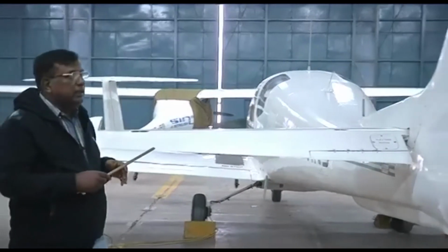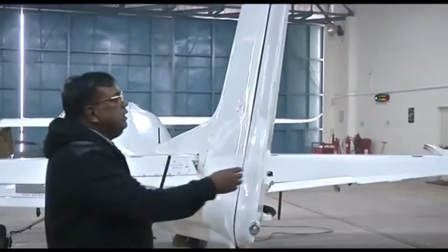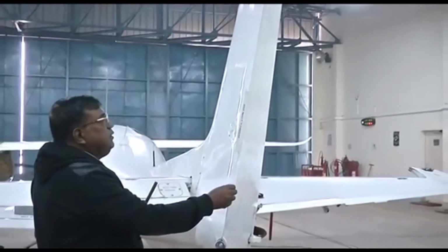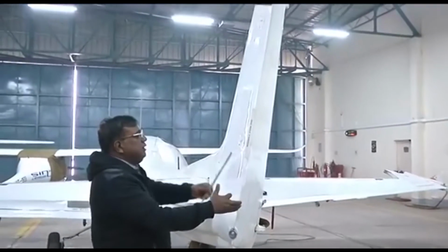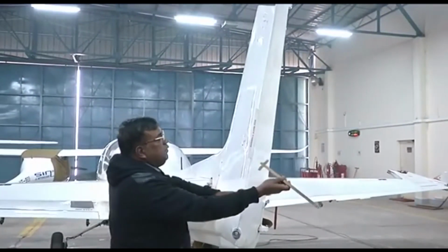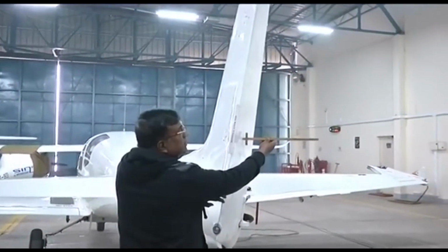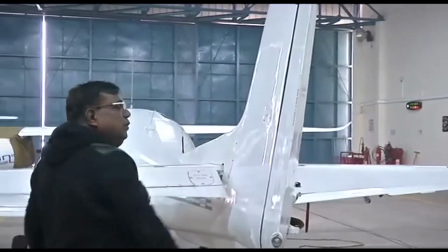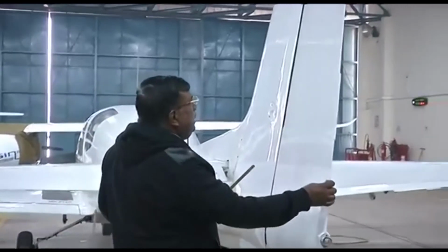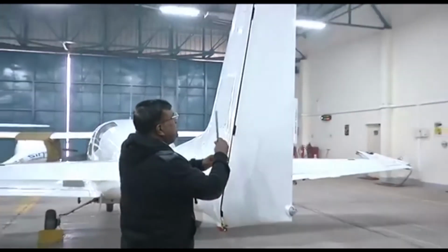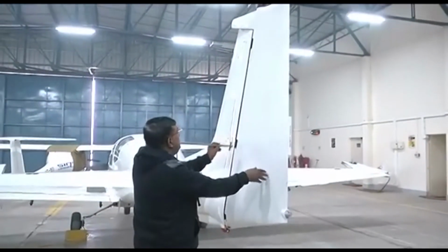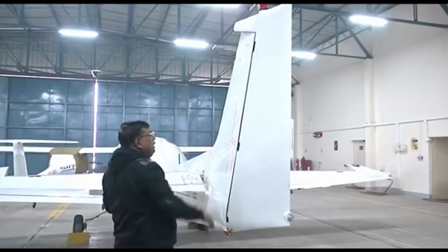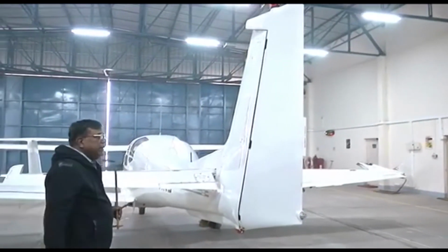Similarly, for the directional case, you could easily see if we deflect the rudder this way, and the airplane is moving in this direction, it will generate a force in this direction, and that force will give a yawing moment taking the nose towards left. And if I do it like this, then the force will be towards me, and this will give a yawing moment which will take the right wing back, right.